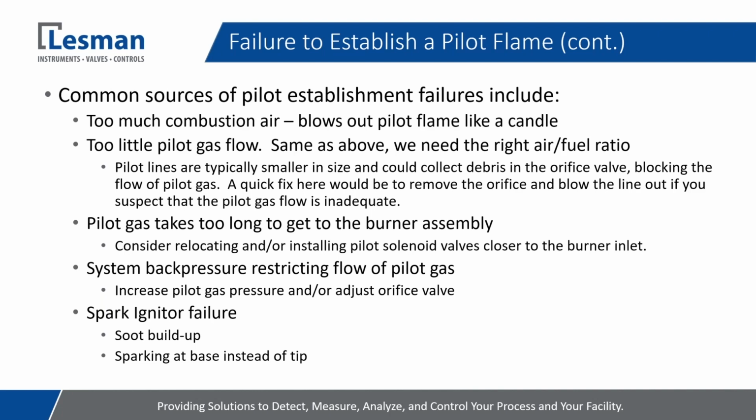We could have ideal air and gas going to the pilot, but we just could have a bad spark igniter. Just like any electrical component, they could be prone to failure. Common spark igniter failures that I've seen is that there's been soot built up. This is common in applications where you either have a continuous pilot or you have a pilot that's set up too rich. Right at that zone of mixing where the spark is located, you could have a pocket of excess fuel, and that could cause buildup on the igniter. So you can either replace it or clean it off and put it back in.